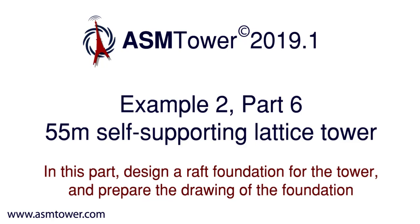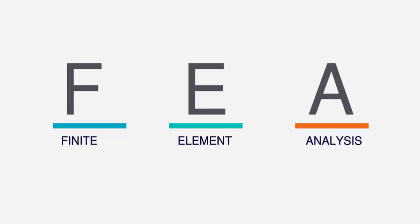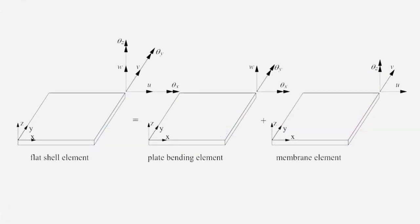We are going to design a mat foundation for this tower. In ASMTower software, the design of the mat foundations depends on the analysis of finite elements. It's not just spreadsheets with simple calculations. ASMTower uses shell elements to model the mat with iterative analysis to solve the problem of contact with the mat on the soil. After the analysis is completed, a detailed report is issued.